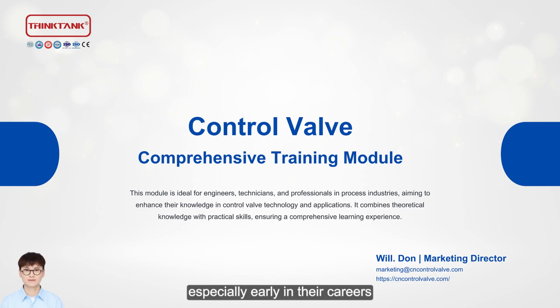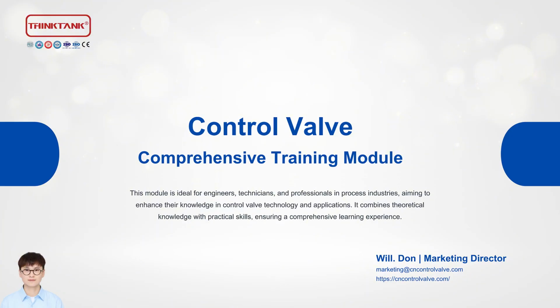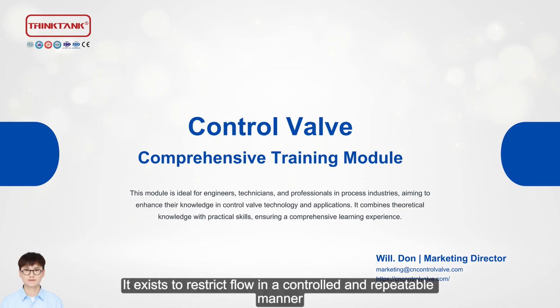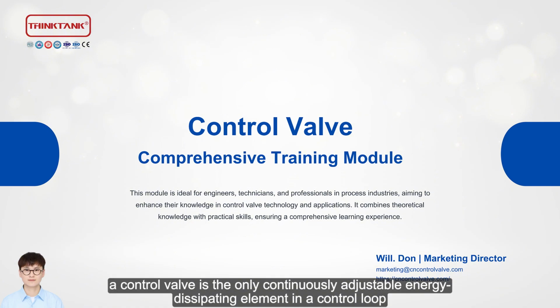Most engineers, especially early in their careers, think of a control valve as a valve that opens and closes automatically. That definition is incomplete, and in practice, it leads to bad engineering decisions. A control valve does not exist to allow flow. It exists to restrict flow in a controlled and repeatable manner. From a physical standpoint, a control valve is the only continuously adjustable energy dissipating element in a control loop.